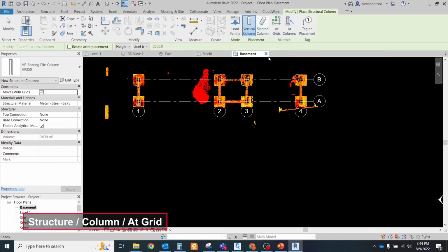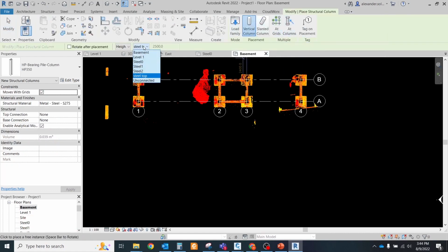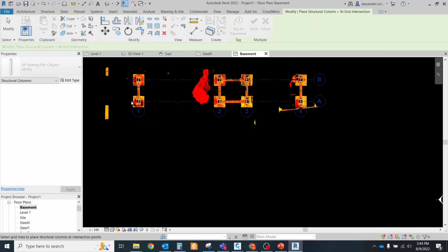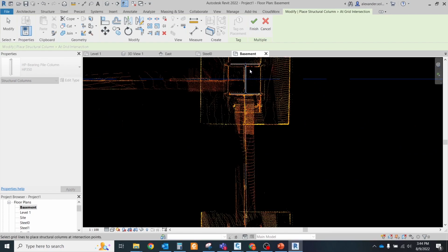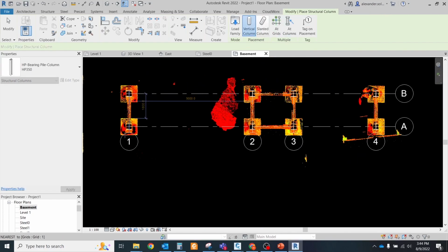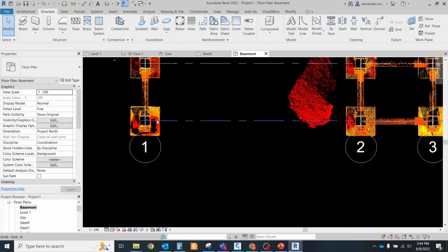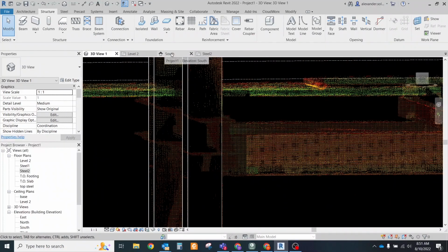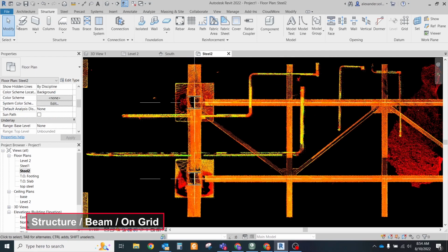After that, you go to the structural column, select the appropriate column from the families and click the Add Grid button. Select all axes to be used to place the steel elements and click OK. All columns will be placed at the intersection of the selected grid lines and extended to the specified level. For horizontal beams, you could use the same axes, but you should use another tool.